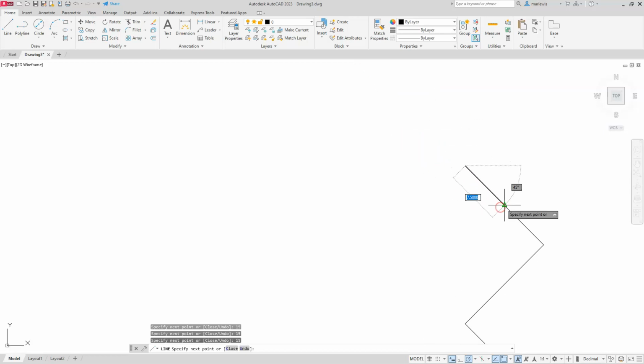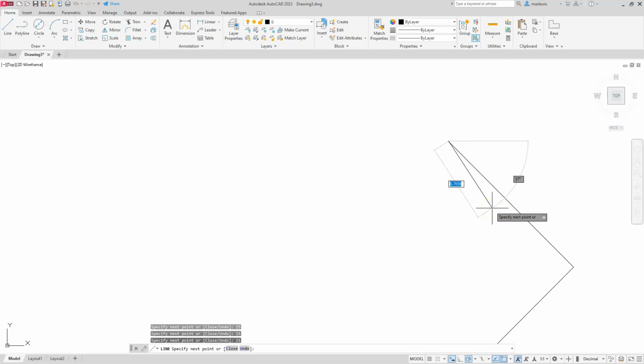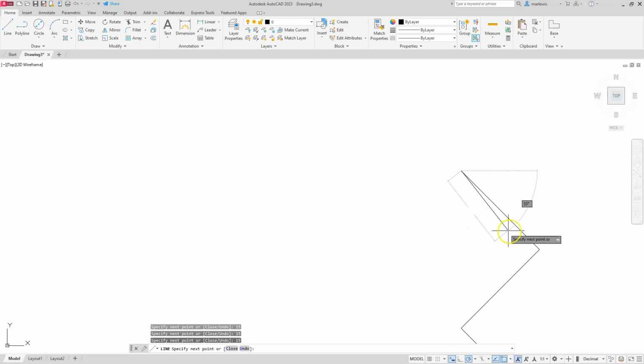All right, and now we're starting to get to some stuff where it's sitting at 105, right? So in this one, instead of figuring out the math, I will count it out. So I'm just going to go back. This is 15, remember? And sometimes you'll see that I got the OSNAP tracking on that little plus there, and it's trying to take control of my cursor. If you scroll either in or out with the mouse wheel, it will clear that.